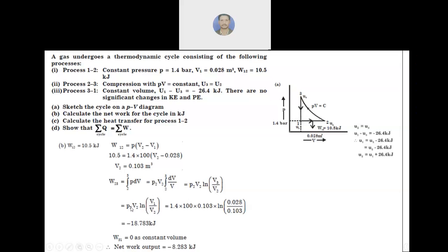Now in this equation, you know P2? Yes, you know. Why? Because process 1 2 is constant pressure process means P1 equals to P2. So P2 you know. What about V2? Here you have calculated V2. V1 given in the question 1028. Put all these values. You will find the work done for process 2-3. Okay?